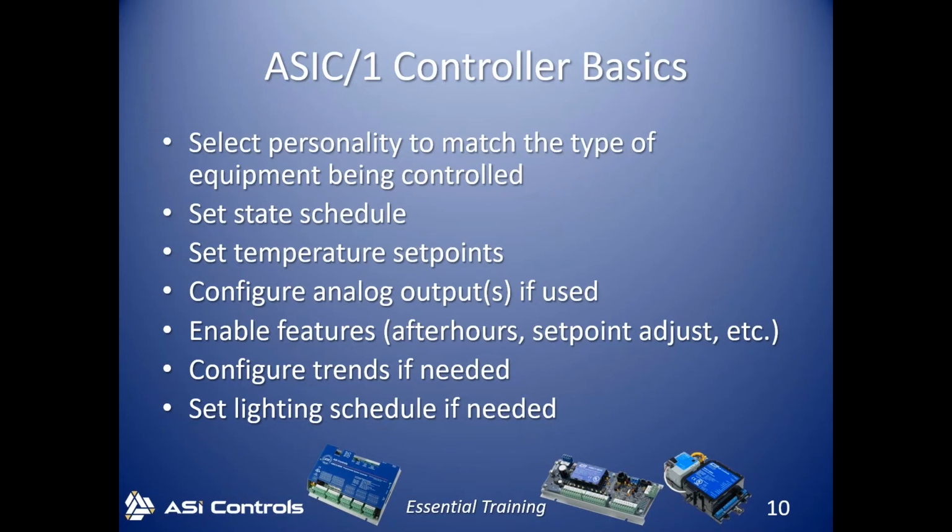I don't think it gets used that often because I don't hear that many questions. I think lighting is usually covered under a separate contract compared to HVAC in a lot of cases. But it's in there. It's intended to control the zone lighting for the same zone that it's controlling the temperature. And so it can either have a separate schedule or it can just follow occupancy too. Whenever occupied, turn on the light.